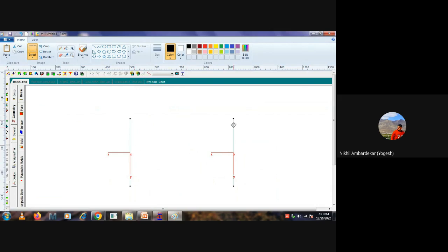We have one wall here and another wall here. So this is the internal side. We want to apply the water load here. So for this, which direction are you going to apply? Against Z, sir. Against local Z. Okay. Means you will provide the minus sign.